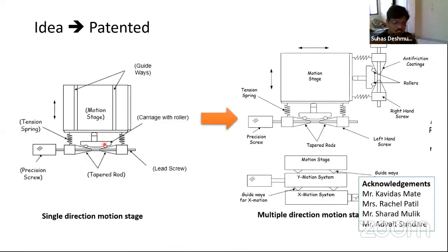In this case, we decided to have only one single stage, which is spring loaded, and this motion is generated in the vertical up and down direction. So whenever you have a rotation of this, it will create one motion. And if I provide an angle that is less than that, there is de-amplification, and if it is more than that, amplification will happen.